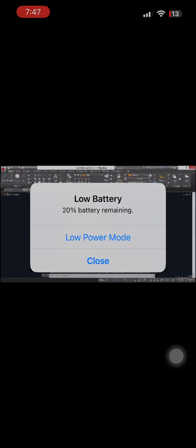If I want to go back in, I can just click on any part of that array and make some changes. However, I no longer have access to the chair array within this array, this nested chair array. If I wanted to change that, I could, but I'd have to explode this overarching array. I can click this Explode button, select the array object and press Enter. That blows away that data structure, and now I have individual objects here. So here I have access to this array, and I can change, say, the number of columns to 1 and close that. So I could have sort of a one-off training desk with just one chair at it.